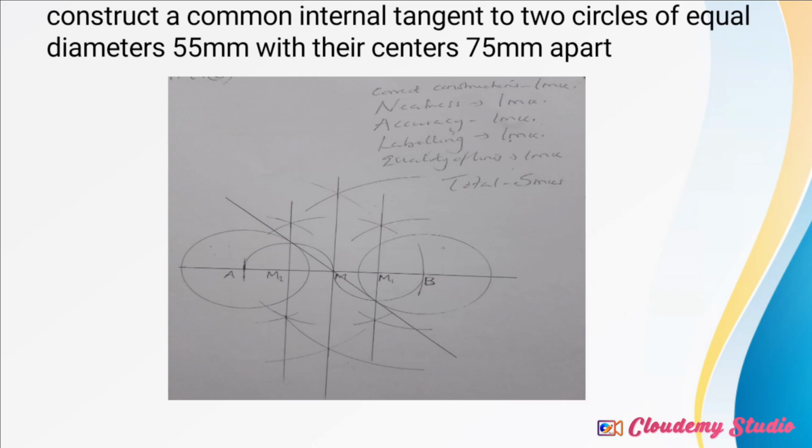At the same time, I do that on the other side, that is between points A and M, to get the midpoint M2. After that, the next step will be starting at point M1, which is the point that is in between A and the midpoint. I'll draw a semicircle that is going upwards. So the semicircle will touch point A, and the second point will be at point M.